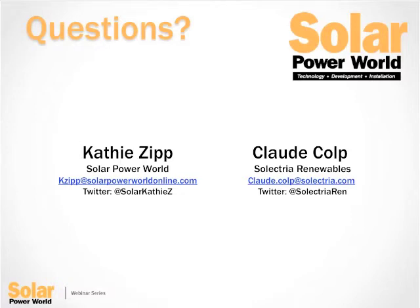So the rapid shutdown requirement was developed to allow people that are able to curtail the output with, say, an optimizer slowly, comparatively to an arc, to 10 seconds. When an arc is detected, the shutdown mechanism happens in fractions of a second. So there are kind of two competing abilities. So it just so happens that in designing an arc fault combiner box, it also has the ability to accommodate rapid shutdown. I think that's a good explanation, Claude.